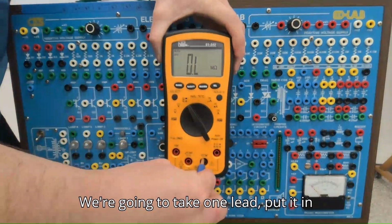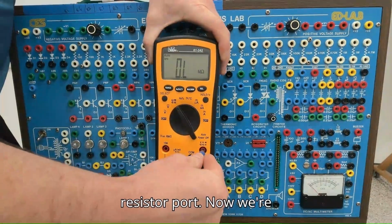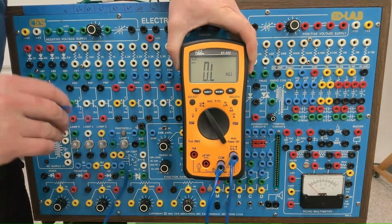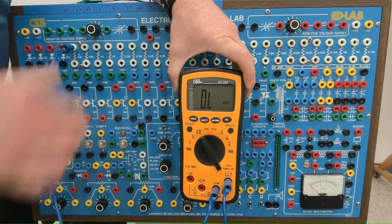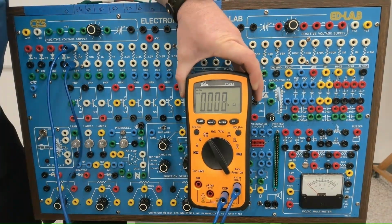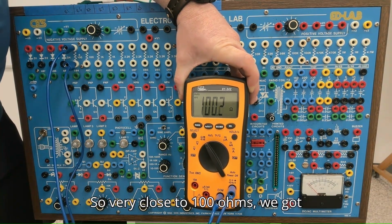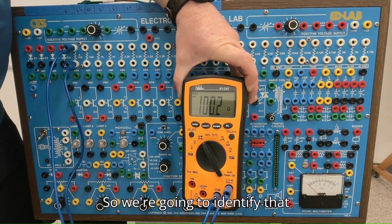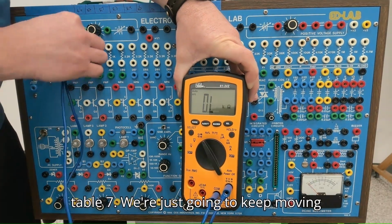We're going to take one lead and put it in our common port. We're going to take our second lead and put it in the resistor port. Now we're going to take the resistance of each of these values here. We're going to start with R1, the furthest left resistor. Very close to 100 ohms, we got 100.2 ohms. So we're going to identify that measurement and locate that into Table 7. We're just going to keep moving on down the line here.